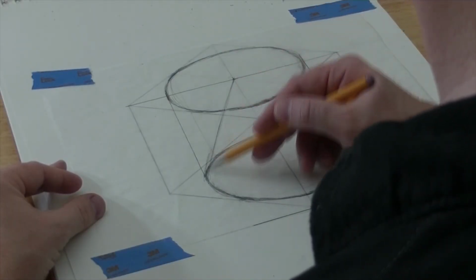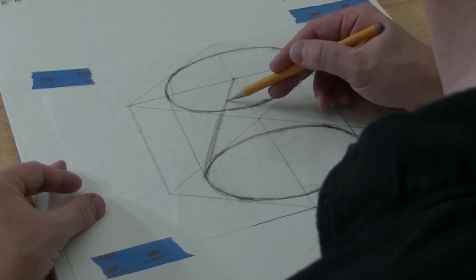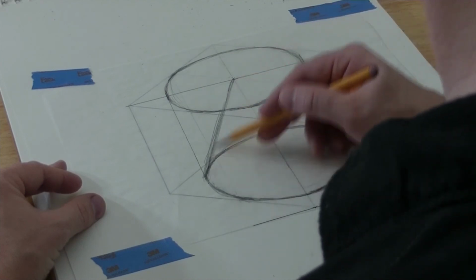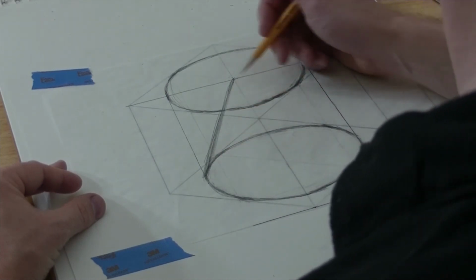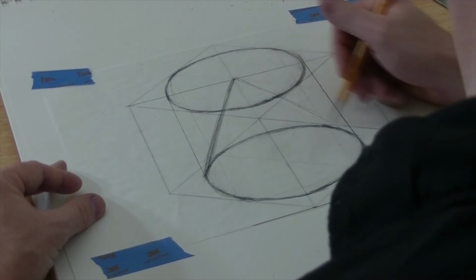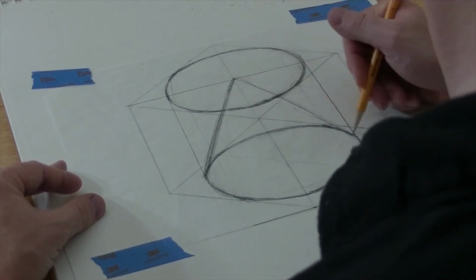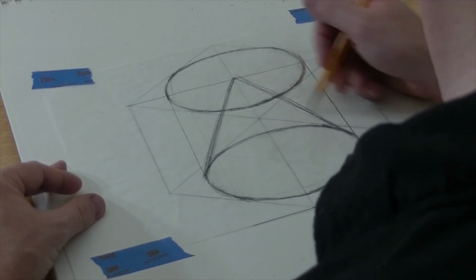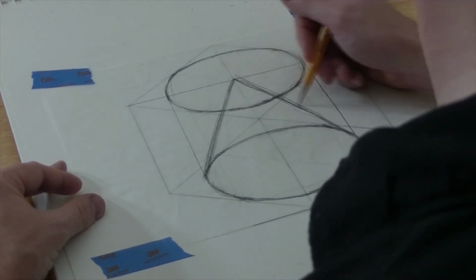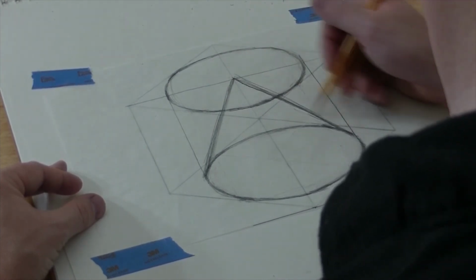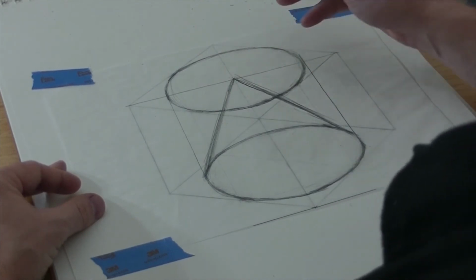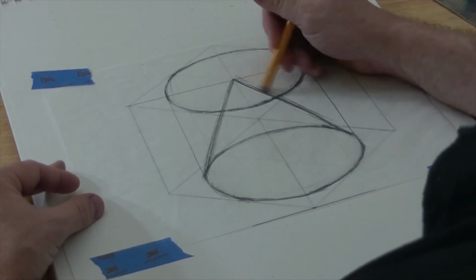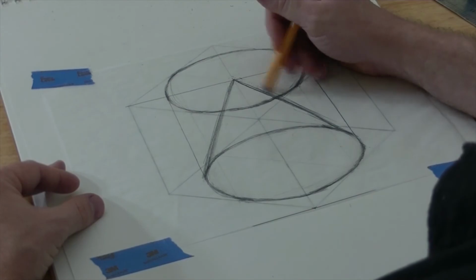Then draw lines from the center point to the outer edges of the bottom ellipse, being careful just to touch the edge of the ellipse. Don't let the lines cross one another. As with the cylinder, the outside lines making up the jacket meet the ellipse at tangent points, but on the cone, they aren't at the far edge of the ellipse because the jacket of the cone comes in at an angle. Okay, start.